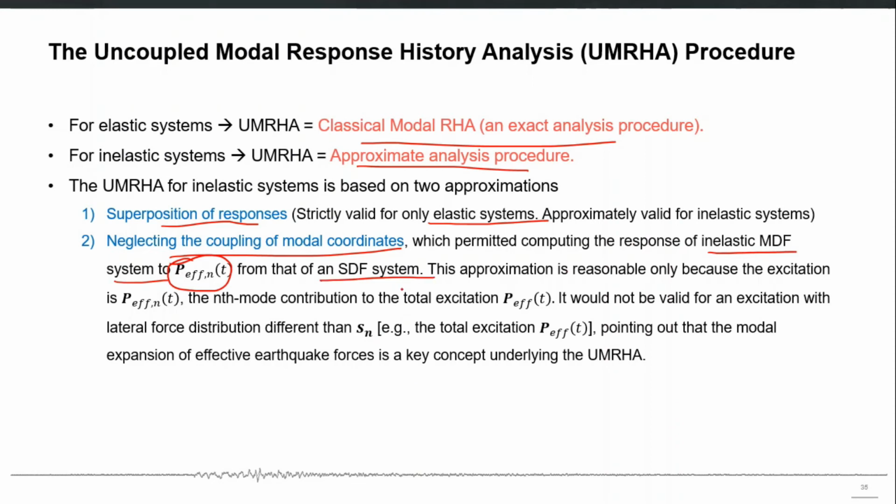This approximation is reasonable only because the excitation is P effective, the nth mode's contribution to the total P effective. It would not be valid for an excitation with a lateral force distribution different than Sn, pointing out that the modal expansion of effective earthquake forces is a key concept underlying the UMRHA. So this modal expansion of effective earthquake forces is the key concept on which the whole UMRHA procedure is formulated.